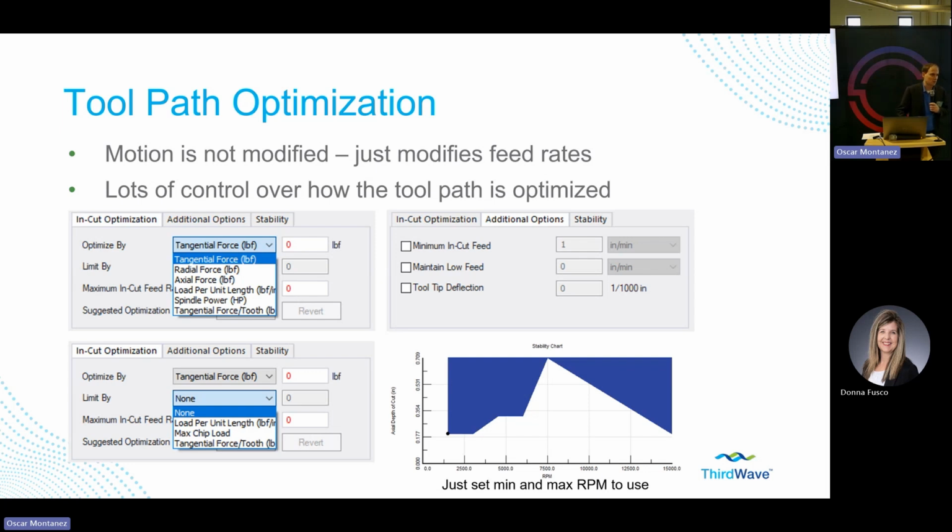So you can go out and understand what the modal analysis for your tool and your workpiece is. You can bring that in, and Production Module will attempt to adjust the RPM slightly so that you are able to stay within a stable cutting zone. That does take a little bit of extra effort to get in, but I'm sure a lot of you are familiar with tap testing. That seems to be the easiest way to do it, but there are many ways that you can derive that and bring it in, and PM will use it to maintain a stable cut.